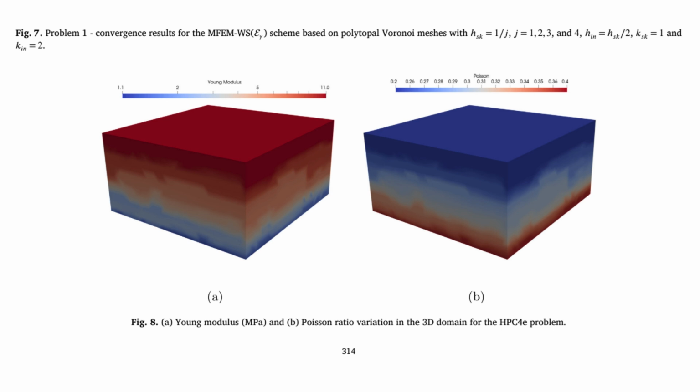Well, it's nuanced. The errors in the main stress and rotation fields are primarily driven by that coarse skeleton discretization, gamma. So you'd expect maybe order l+1 convergence, which is standard. Okay, that sounds normal. But here's the kicker. Because you have all that freedom inside each polyhedron with the fine scale gamma, you can get much better accuracy for the divergence of the stress, nabla dot sigma.